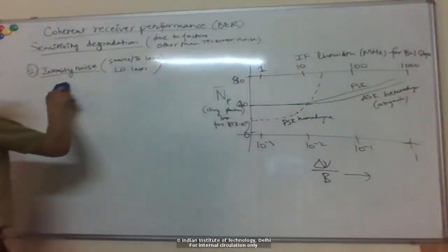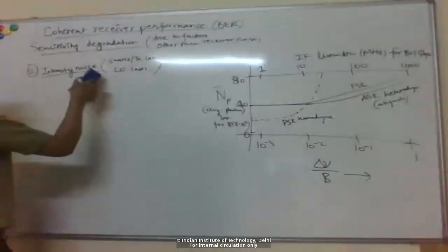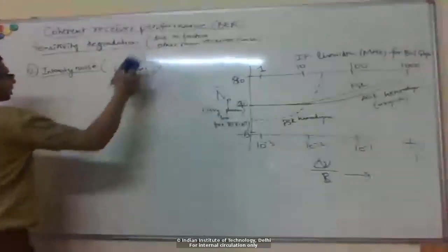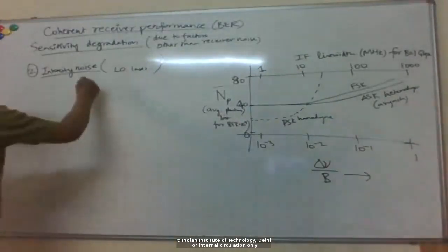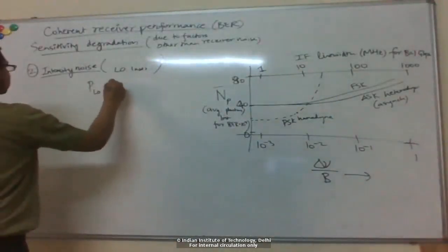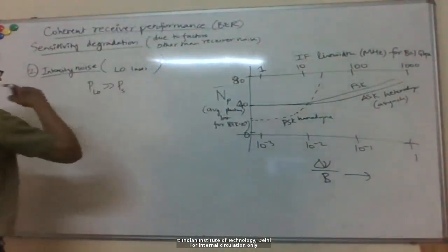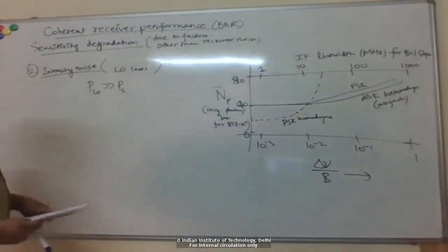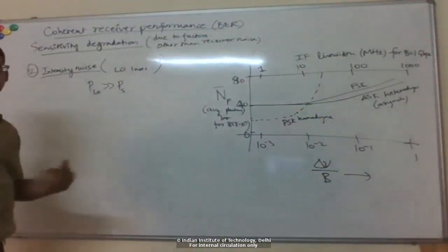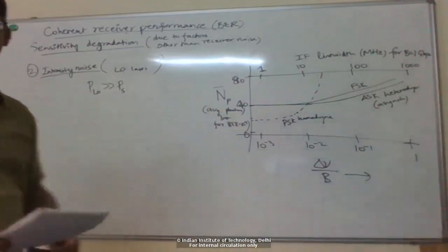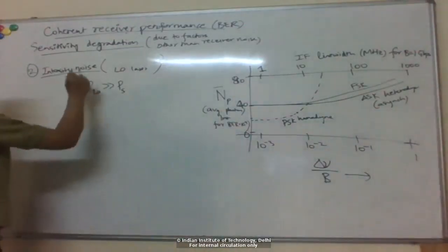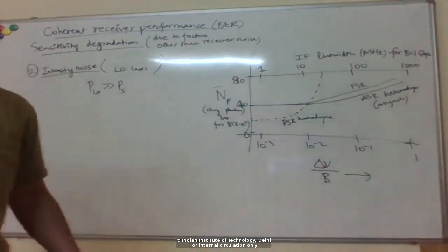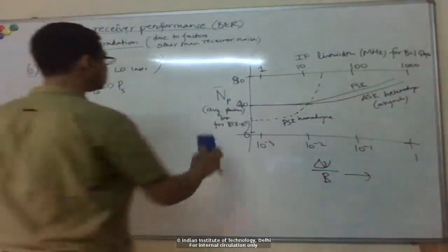And in this case, basically the main source of noise will be the local oscillator, because recall that we set the local oscillator power to be actually much larger than the signal power, received signal power, right? And we know that the mean optical power... So basically, mostly the local oscillator intensity noise is what contributes.